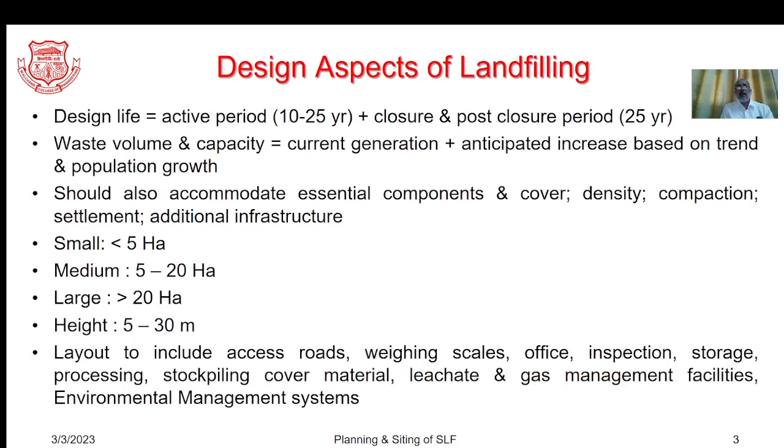The design of the landfilling we will be discussing shortly. However, you have to think about some aspects, such as for sanitary landfill, we assume the active period to be 10 to 25 years, whereas we have to have the closure and post-closure plan ready for the next 25 years.